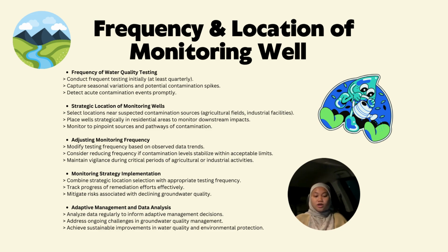Strategic location of monitoring wells, which is to select locations near suspected contamination sources. Place wells strategically in residential areas to monitor downstream impacts. Monitor to pinpoint sources and pathways of contamination.